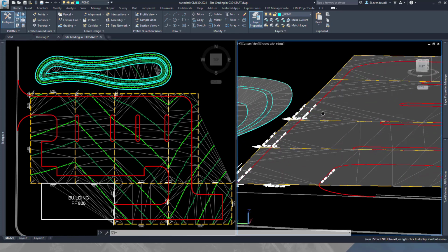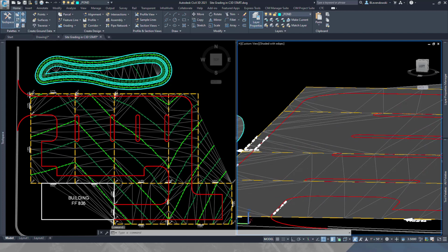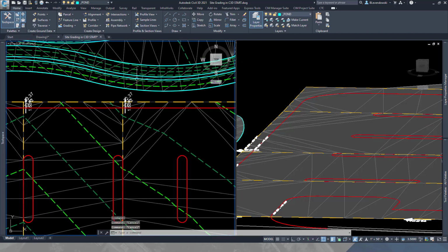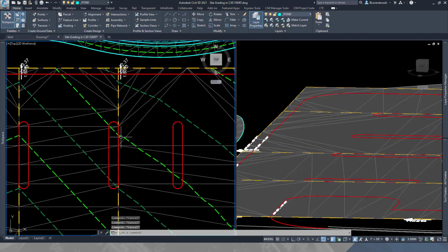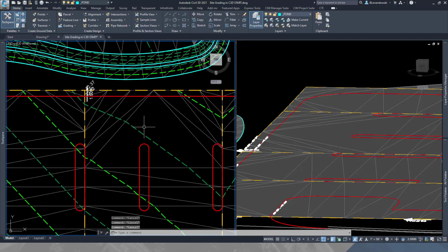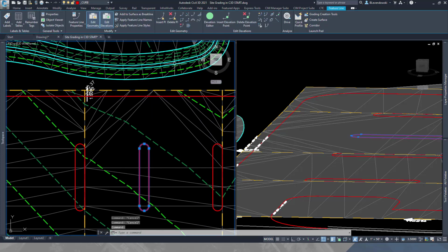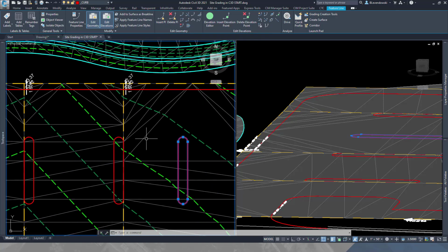And so the real common way to do that with Civil 3D is to run stepped offsets just like we did here. Some people run, there's options to run a corridor region around here. I've taught classes on that as well. I think it's a pretty clumsy workflow, in fact. I think this is easier to understand using just feature lines, but taking advantage of some of these things I'm after here. So running stepped offsets, we'd run through and run that on all of these different feature lines. It takes a little bit of time. It's not too bad though.